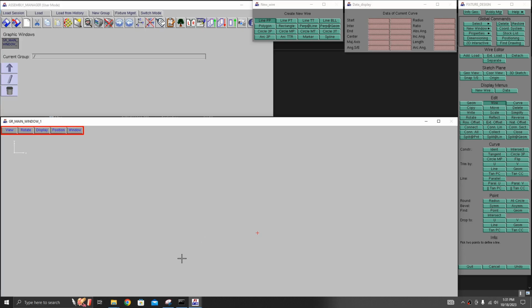If you are not holding for a straight line, wherever you click, the line will come. So for getting the straight line, I will hold the control. So I got the straight line. Now how to change the dimension? Here you might see one arrow mark.